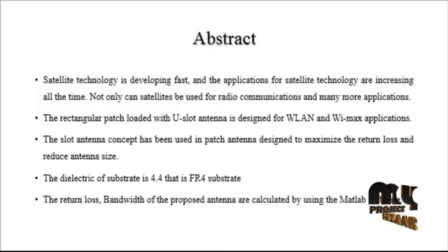In the first two methods, optimization of the probe location is necessary for further enhancement of the 10 dB return loss bandwidth, because the return loss should be below minus 10 dB. The third method, dimensionally invariant, optimally combines the features of the previous two and is developed here to yield the bandwidth performance with minimal or no probe location optimization, and hence is superior to the other two for rapid prototyping.